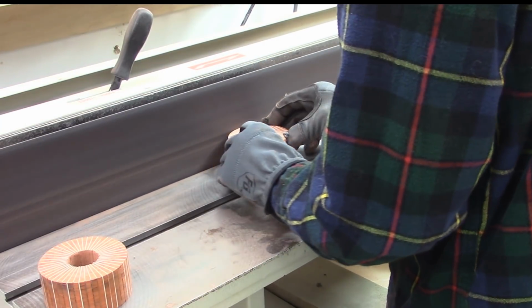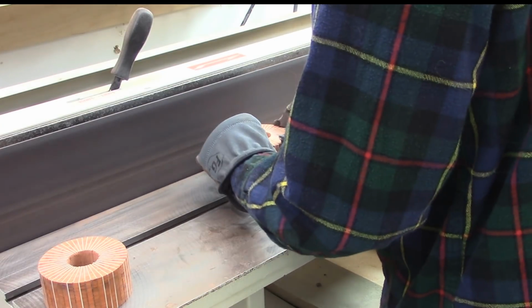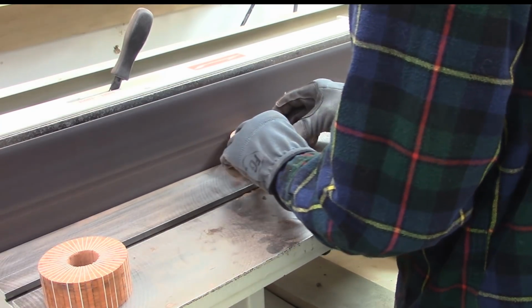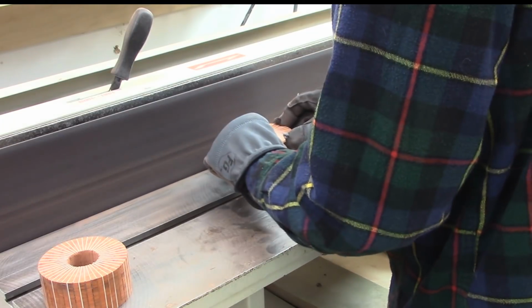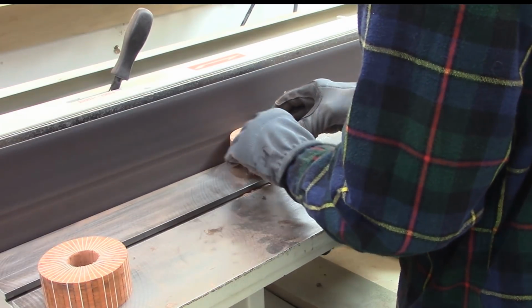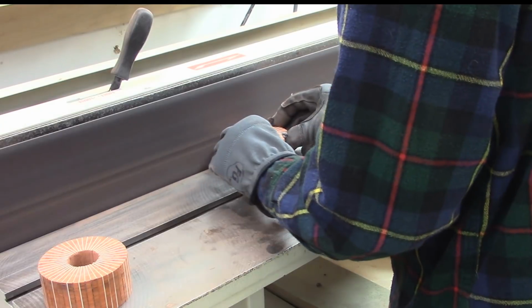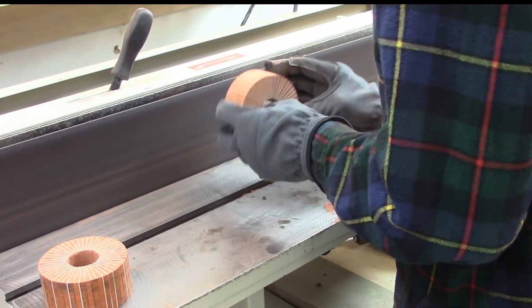Finally, I clean up the disc assemblies on my edge sander. I sand both the faces and the circumference around the disc assembly. I sand the circumference sides so I can easily see the patterns of the segments when the sliced discs are realigned and glued back together in a future step.